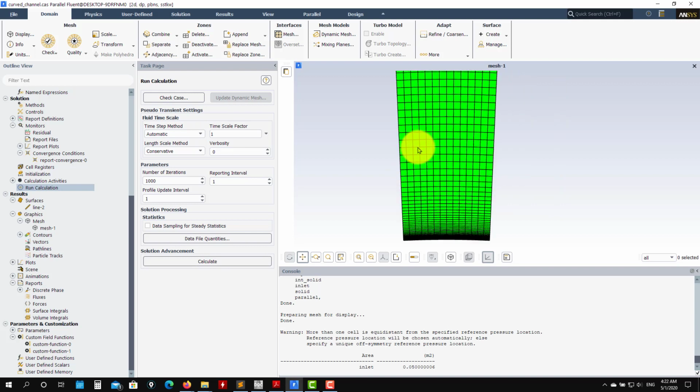It's a huge violation of physical principles, but you can reach steady solutions fast and in a more stable way than using a fully SIMPLE pressure velocity coupling, the SIMPLE or SIMPLEC. Why? Because now you are adding time. Besides the relaxation, you have also time. So this is what it's controlling: the larger value means larger CFL or larger time step.